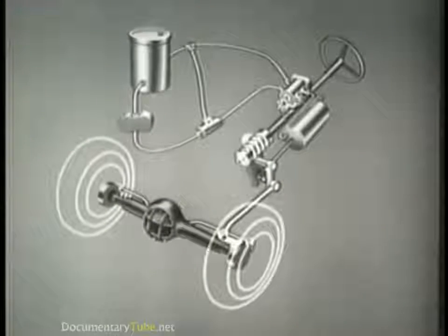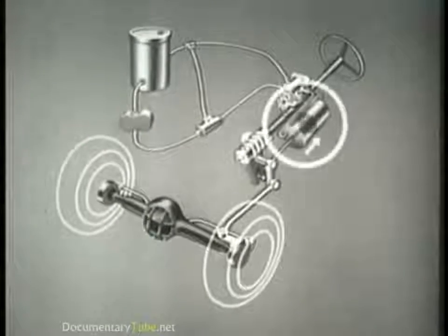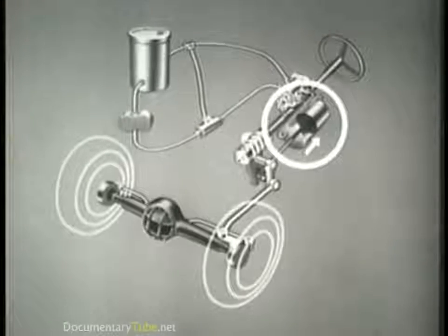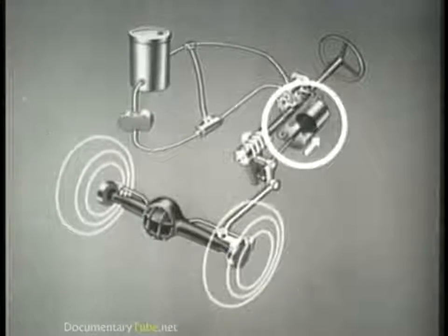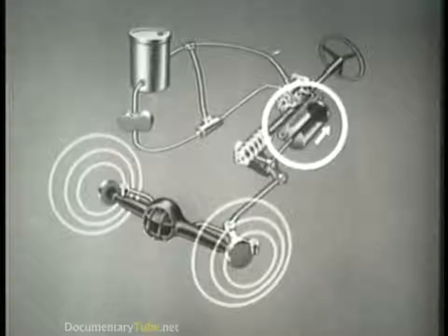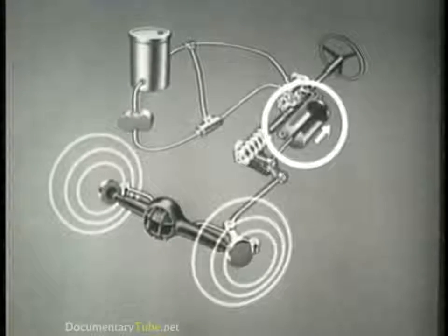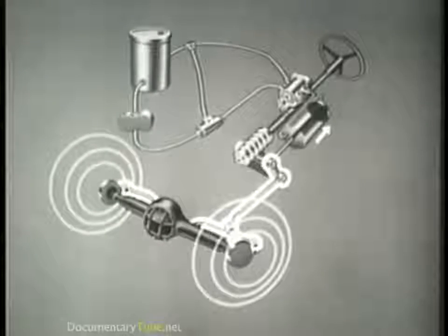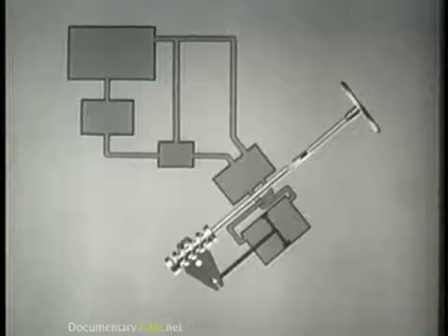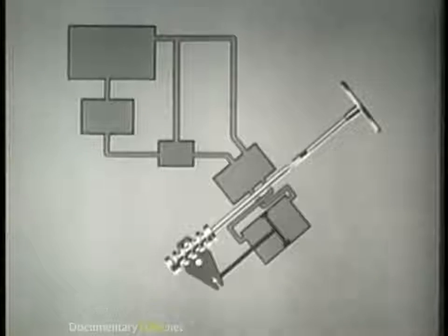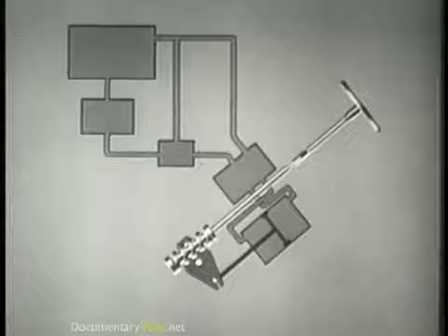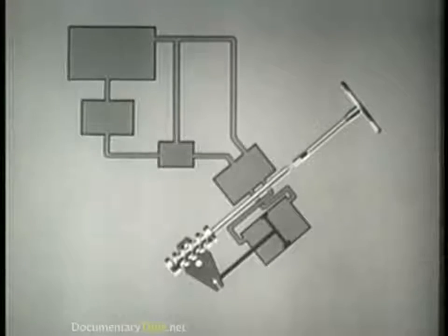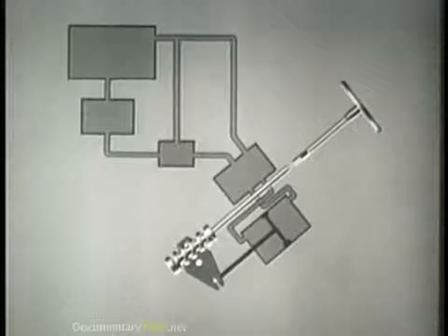In like manner, as the fluid pressure is increased on one side of the piston, it will be moved by pressure differential, aiding in steering the front wheels through the steering linkage. To aid in illustrating the internal function of the hydraulic system, a schematic diagram will be used. The steering linkage from the pitman arm lever to the front wheels will not be shown.